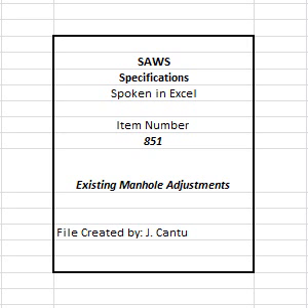A. The contractor shall conform to detail DD 852 drawing series as modified herein and install manhole ring encasements for manhole adjustments and for ring and cover replacements and reinstallations. 19. Material excavation from around the manholes shall be replaced with flowable fill in accordance with these specifications. 20. All excess materials shall be disposed of by the contractor at his own expense and in an approved location.